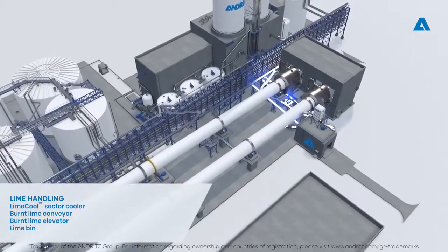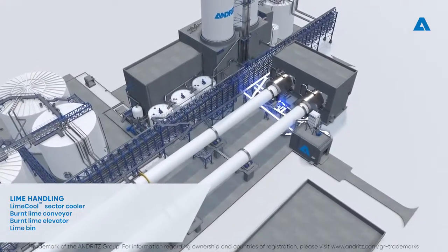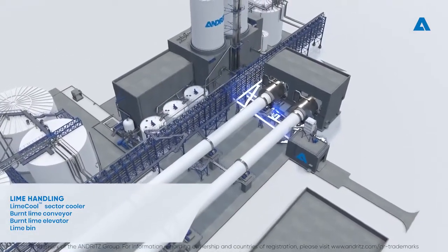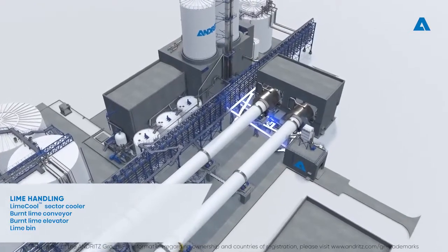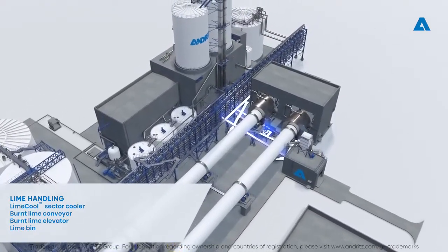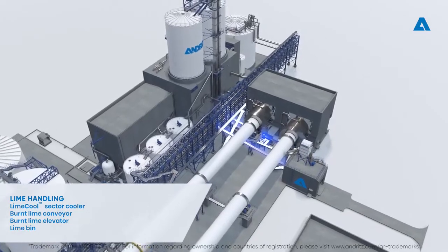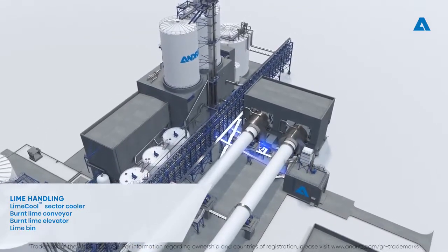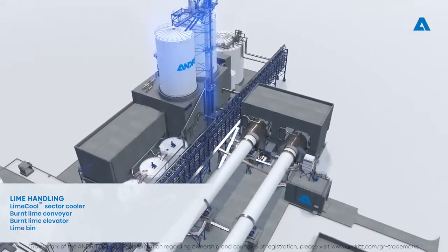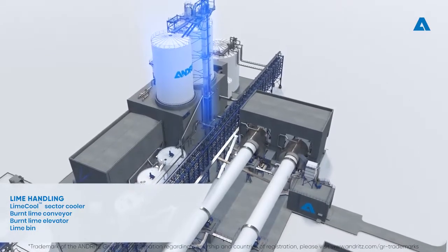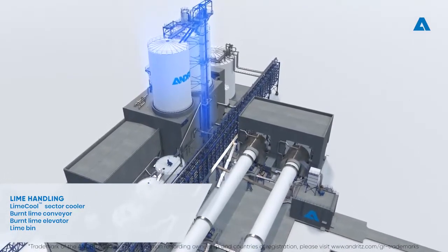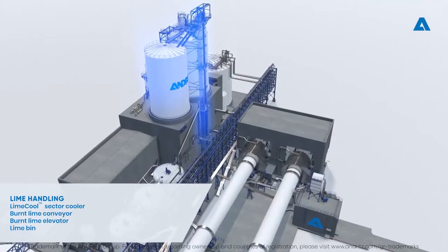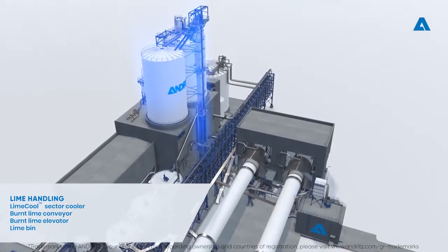From the sector cooler, the fine lime falls through the diverter gate directly to the burnt lime conveyor. Bigger lime particles drop to another diverter gate and then via a crusher onto the burnt lime conveyor. From the conveyor, the lime falls onto the burnt lime elevator, which will lift it further into the burnt lime bin.